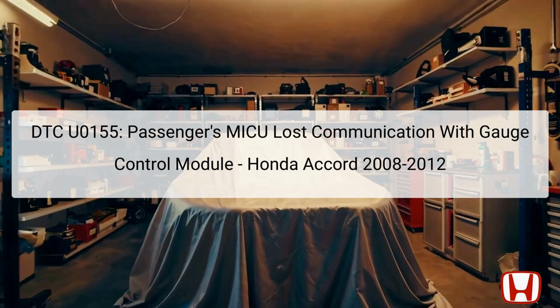The Diagnostic Trouble Code, DTC U0155, indicates that there is communication loss between the passenger's microcomputer interconnected unit, MICU, and the gauge control module in the 2008 to 2012 Honda Accord. This communication is critical for ensuring that the gauge control module receives information from the MICU, allowing it to display accurate vehicle information like speed, fuel level, and engine temperature.